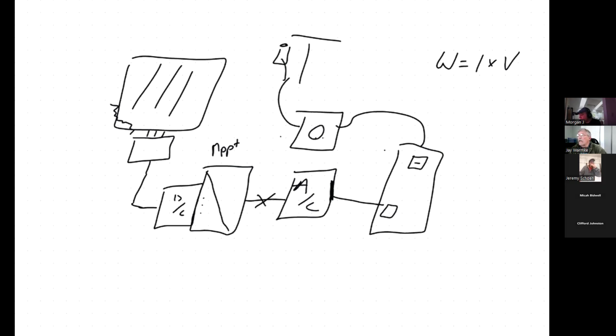You can measure water pressure without water flowing. You can measure volts without electricity flowing, but you cannot measure amps. You cannot measure current unless it's going somewhere, unless it's flowing to a load. Without a load, there's no flow of electricity.